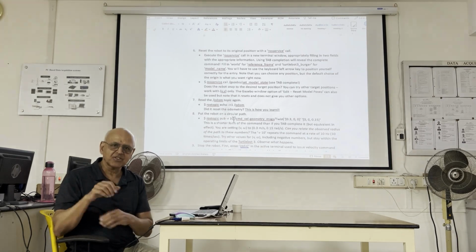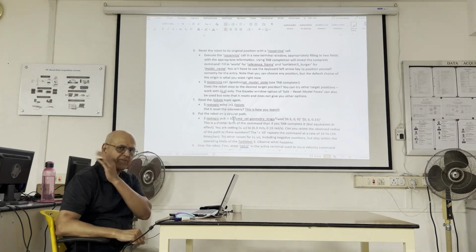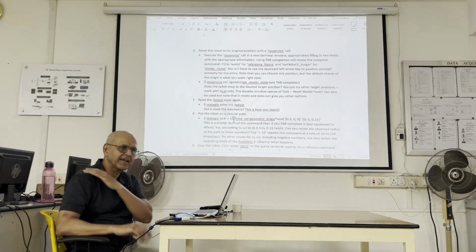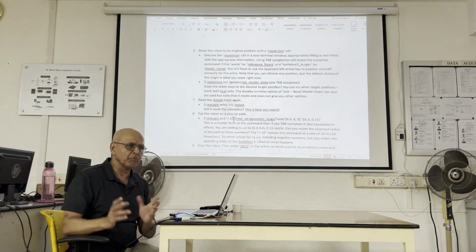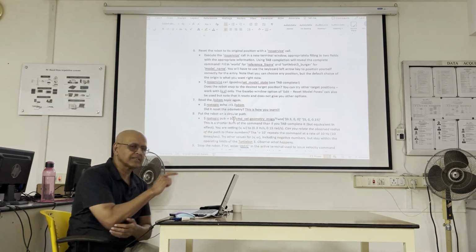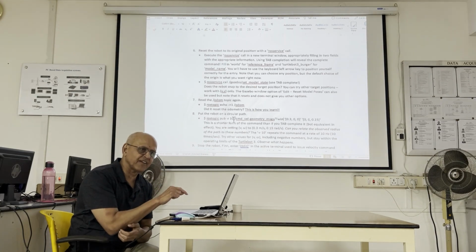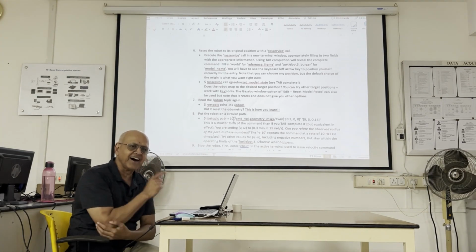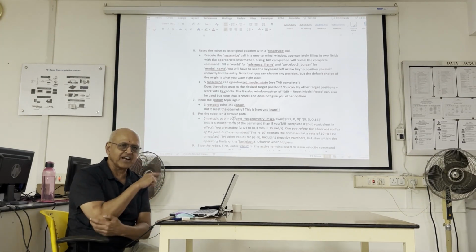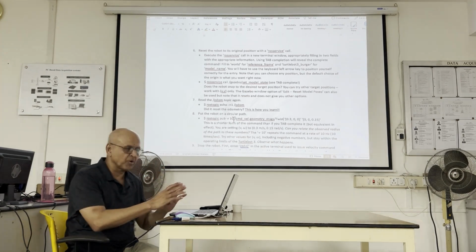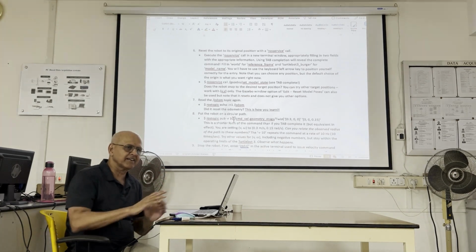Basically if I'm the driver, people should tell me keep driving, keep driving. The moment I don't hear this tap, I'm supposed to stop. All motors are supposed to have it. Now, Turtlebot 3 has not programmed that feature into their robot. Other robots have. So Clearpath Robotics, another company, their robots, the moment you stop commanding it, it will come to a stop.